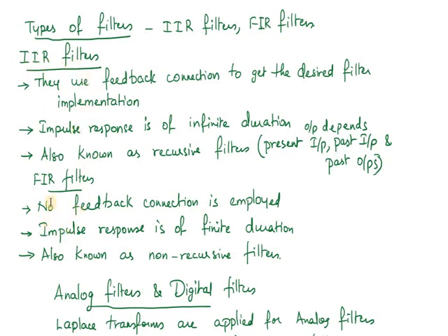Next, if we see the features of FIR filters, in these FIR filters there is no feedback connection from the output to the input, and their impulse response is of finite duration, and these are also known as non-recursive filters. So in these FIR filters, the output depends upon the present input and the past input. Okay, so these are finite impulse response filters.